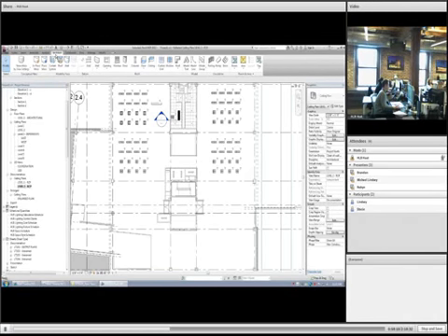The other type marks as well. Exactly. So if it's a particular group that's offending, you can include the tag in the group, which I think you were doing a lot of. We had detail groups, and it was for that reason, in the sense that for our project we had one courtroom that was used 12 times. So we documented one courtroom, we tagged everything, made it look good, so tags were where they should be, and then attached that within the group so that it's copied and pasted without having to adjust. That makes a lot of sense. But we should probably show how to add tags to that group. Yeah, okay.